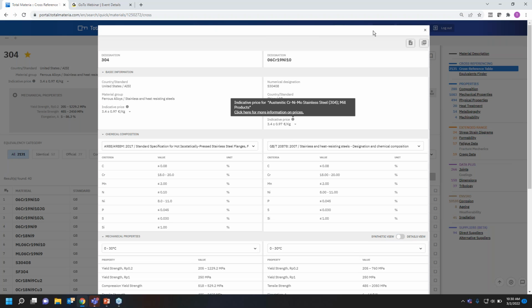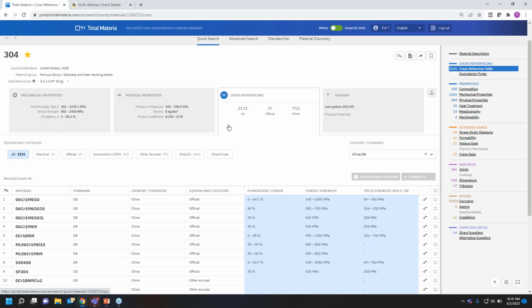All these comparison views that you are making, you can forward to your PDF file. Everything that you're forwarding, you can print to PDF. So it's not a problem. And you can of course also add all these comparison views to your reports that you're making inside the material console. Not only can you compare 1-to-1, but you can compare up to 100 materials at the same time.